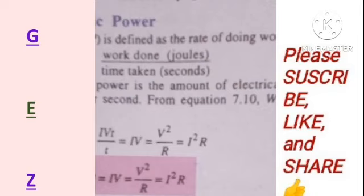So power is equal to work divided by time, but in this case our work is equal to IVT. That is, work is the product of the current, the voltage, and the time taken for that current to pass through. So in this case our power will be IVT over T. That will be IV, and that will be V squared over R. The reason is that I itself is V over R, so that's V over R times V, which is V squared over R. Then you can also change it: since V itself is equal to IR, V squared over R is IR times IR over R, that's I squared R. So there are different ways you can express power.